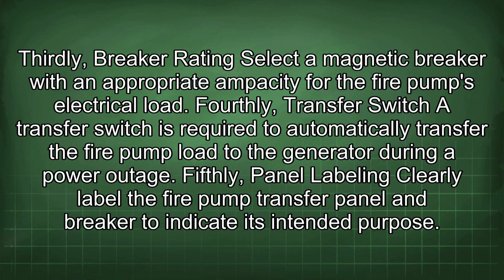Fourthly, transfer switch. A transfer switch is required to automatically transfer the fire pump load to the generator during a power outage. Fifthly, panel labeling. Clearly label the fire pump transfer panel and breaker to indicate its intended purpose.